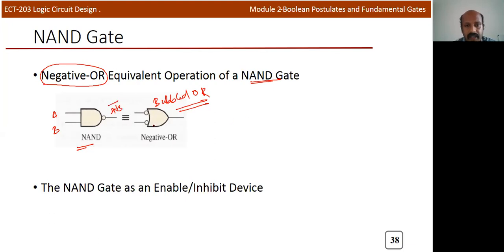When you use this gate, here you connect A, and here it is B. Before applying the input, we make it the complement, so you will get A bar, then B bar when you perform the bubble, which is the NOT operation. Then you need to perform the addition. So this is equivalent to A B the whole bar. We can prove this. Simply write A B, then A bar, B bar, and then A bar or B bar.